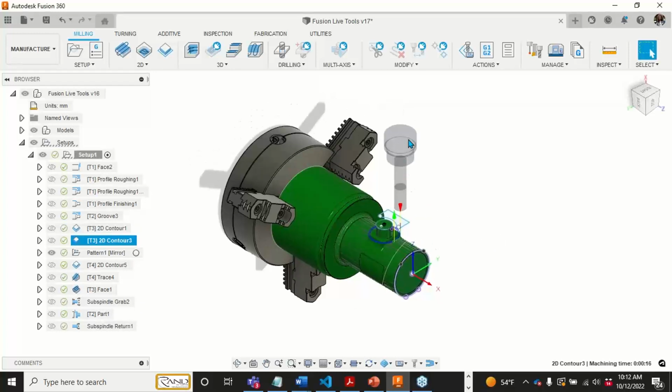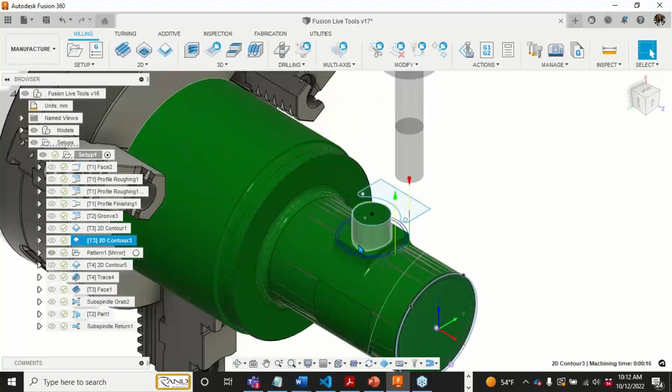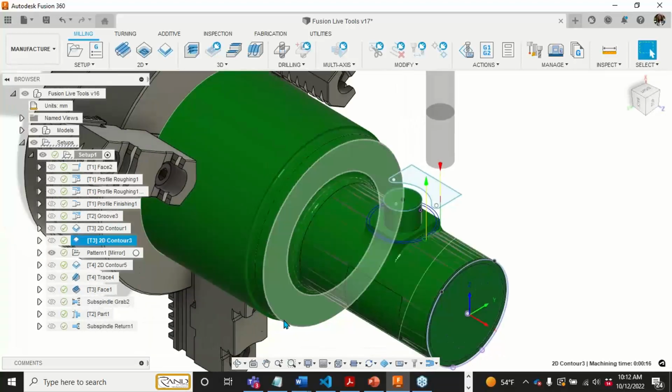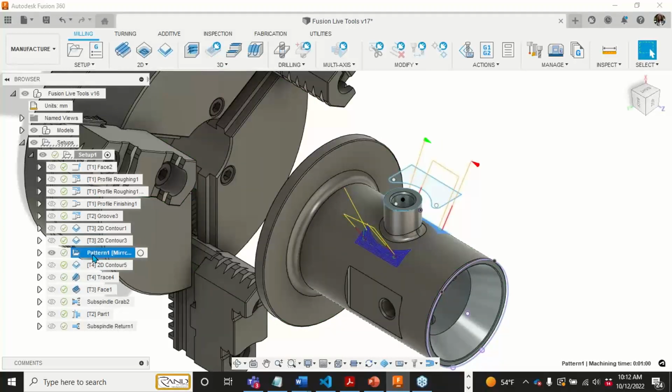And then I've got a live tool mounted normal to the diameter of my part, and I'm able to start whittling material away from that boss and getting it down to that final shape. Okay, and then I'm able to come down here to this toolpath. Now you'll notice what I've done here is I'm assuming that my machine has the capabilities of a Y-axis.